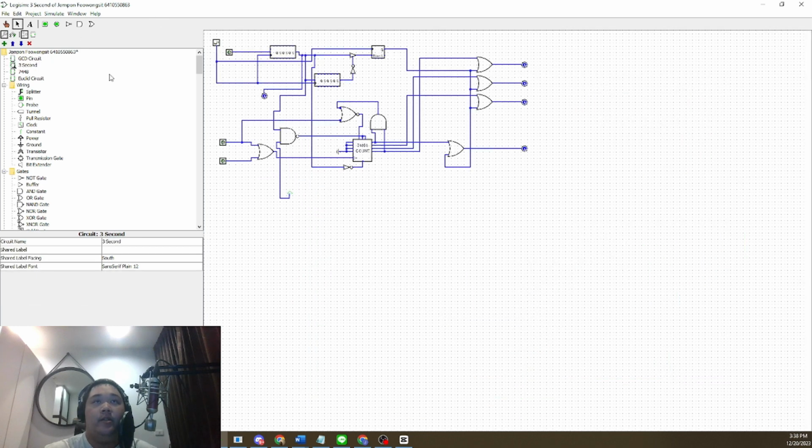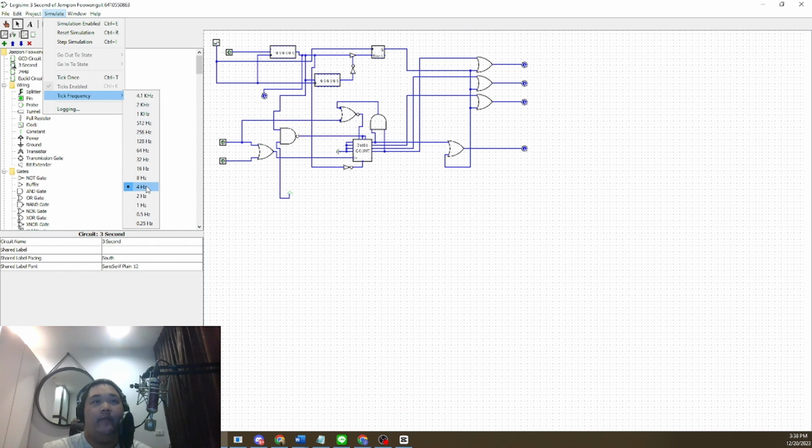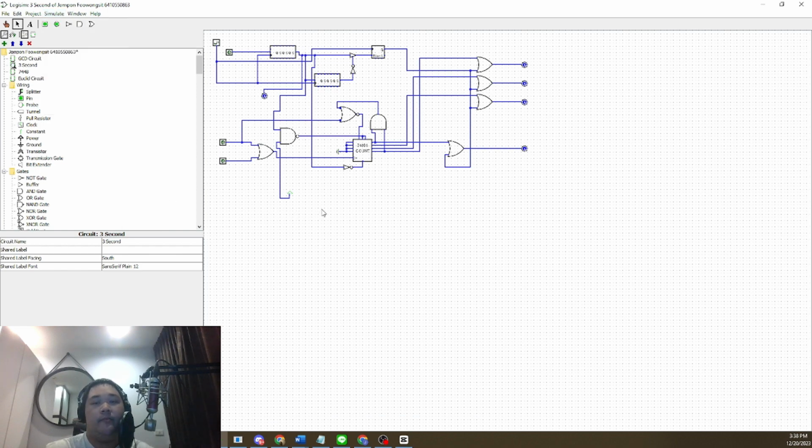So first, the 3 second reset. In it I employ a register in our circuit operating in sync with a clock, at a frequency of 4 Hz or 2 Hz. I choose 4 Hz because it's faster. And we choose 6 states because one state gives us 0.5 seconds. So 6 states times 0.5, we have a 3 second resetting circuit.